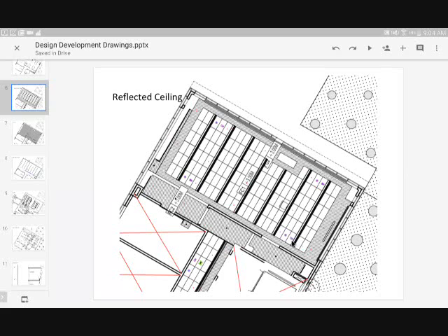And here you find the fire protection. So you will design your own suspended ceiling or reflected ceiling. That is a suspended ceiling that covers all these systems. And on this reflected ceiling plan, you will indicate the lighting, the HVAC, the firefighting, if you have a sound system.